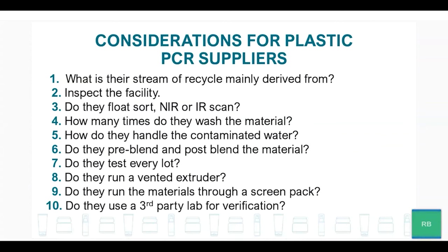When looking for a supplier, you need to be diligent. Ask, what is their stream of recycle mainly derived from? Is it toys, batteries, food containers? Inspect the actual facility and see what and how they sort, wash, and extrude the material. How do they sort it? Do they float, NIR, IR, or a combination? How many times do they wash the material prior to recycling? How do they handle the contaminated water from the washing?